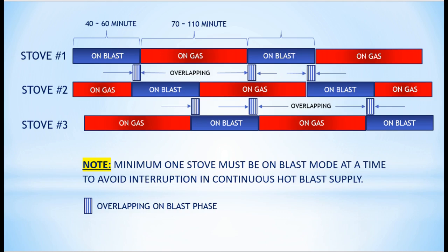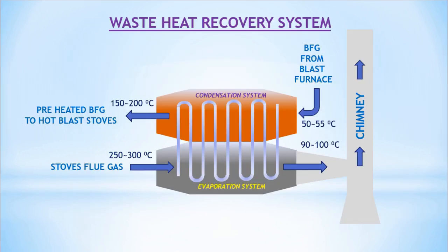Note: minimum one stove must be on blast mode to avoid interruption in continuous hot blast supply. On blast time: 40 to 50 minutes. On gas time: 70 to 90 minutes.